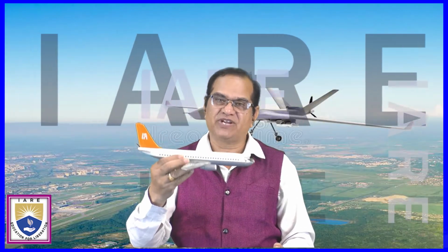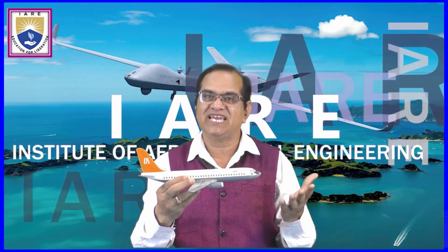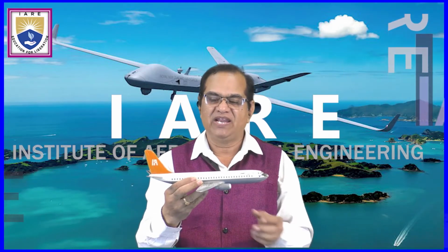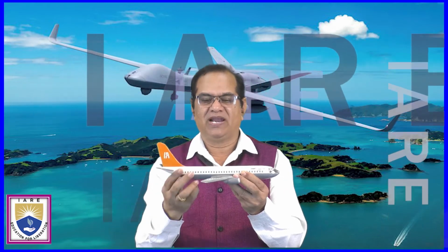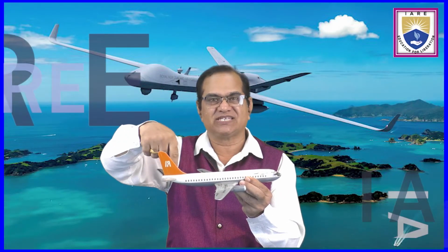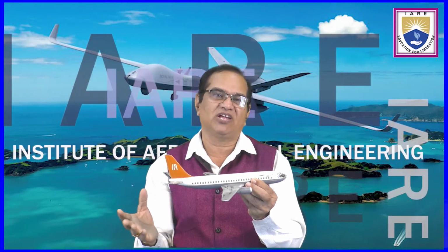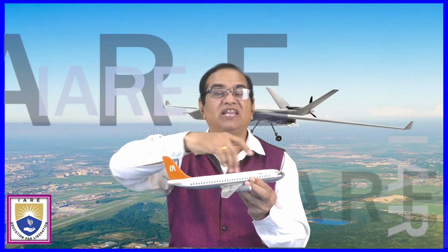Pitching is obtained by the motion of the nose with respect to the lateral axis. If it is going up and down with respect to the pitching axis, we say it is a pitching motion. And if the aircraft wing is going down or up like this, it is with respect to the longitudinal axis, and this motion is called rolling. So rolling of the aircraft is achieved about the axis which is called the longitudinal axis.